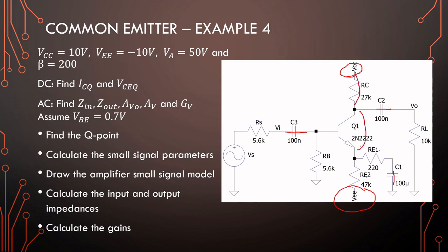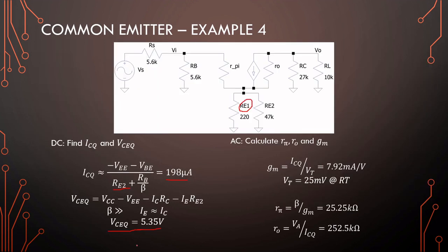In our other examples where we use single rail and 15 volts, it was a third and a third. So what I said about the Q point in video 2 and video 3, you can see that that is a very real thing with these amplifier analyses. Okay, but don't ever use the design equations when doing an analysis. Okay, it's two different things.